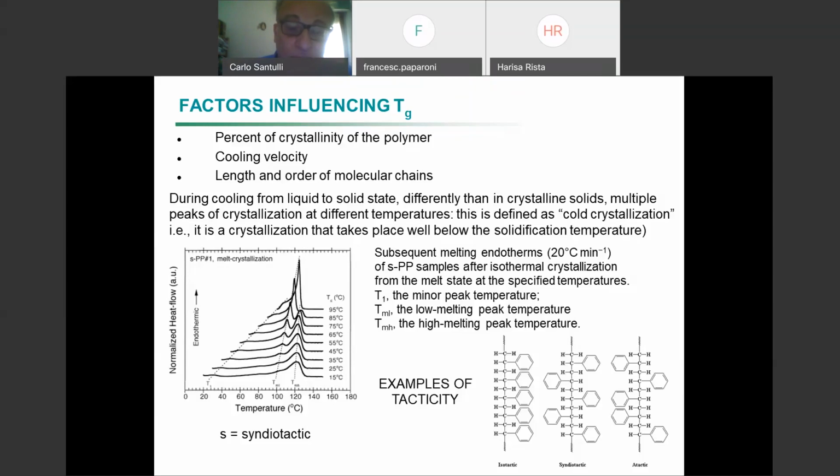And this is important because molding, polymer molding, occurs above the high melting temperature. So we need to know where we are, above the high melting temperature. Of course, since the polymer degrades with temperature, and also because heating more costs more, we tend to be as close as possible to the high melting temperature. We need to be higher than the high melting temperature, but not that much. But since this depends also on how we cool down, which temperature we cool down to, that also controls the width of the solidification interval.